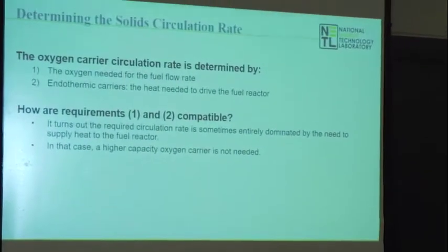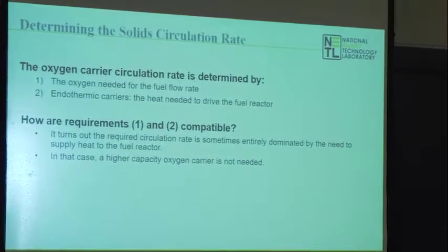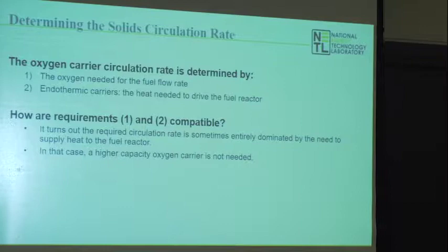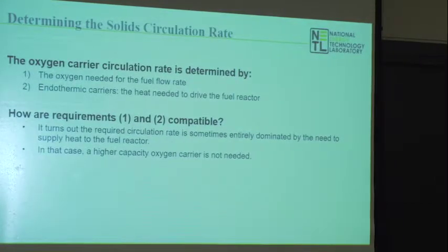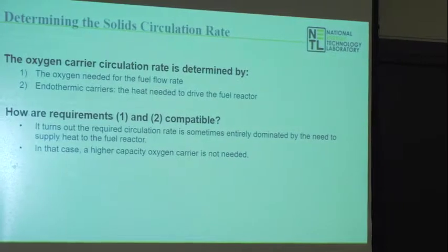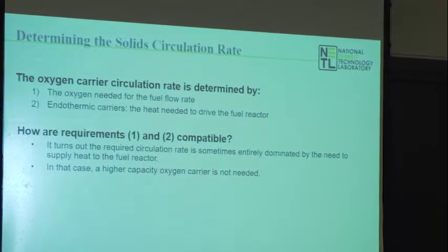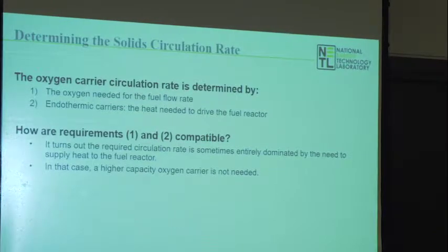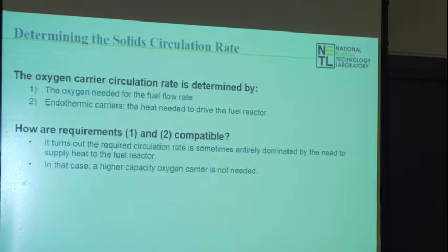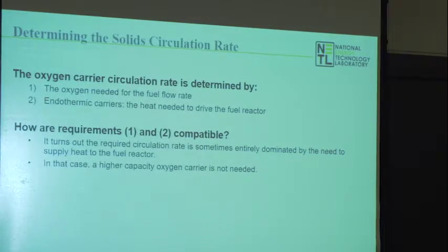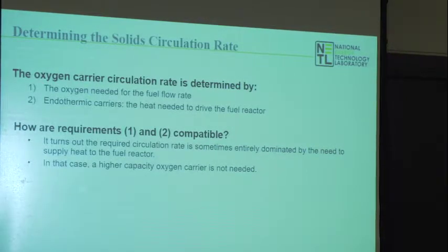But there's more to the story than just oxygen capacity. I'm going to take you back to what we started with, talking about the endothermic and exothermic carriers. Let's focus just for a minute on endothermic carriers. Remember those carriers, you need to put heat into the fuel reactor. Otherwise, it'll just quench the reaction, right? It needs heat to sustain that reaction. And I said, the only way I can get that heat in there, I can't put a steam pipe in, is I bring it over with the carrier.